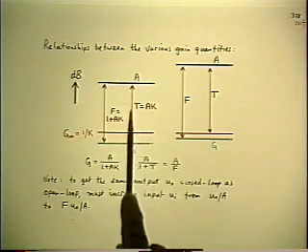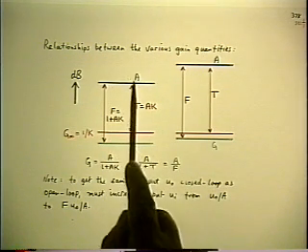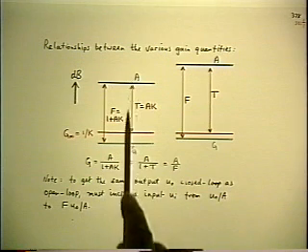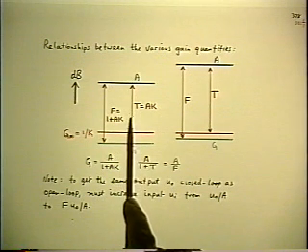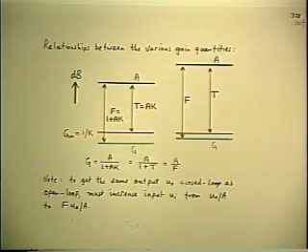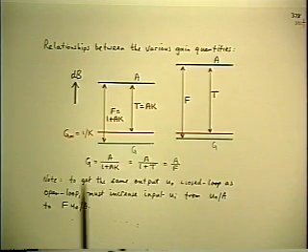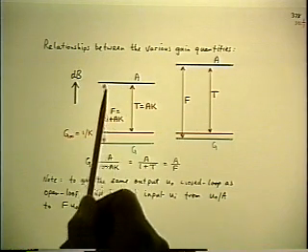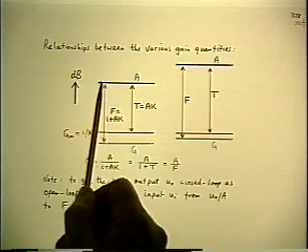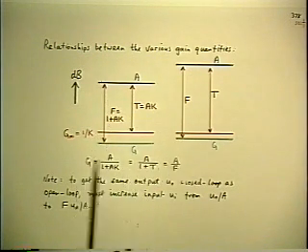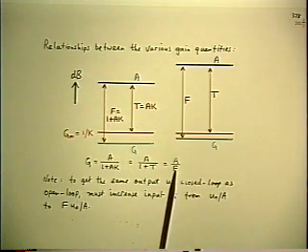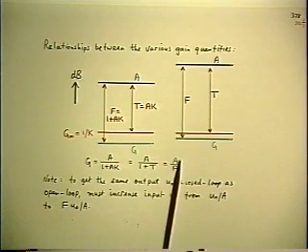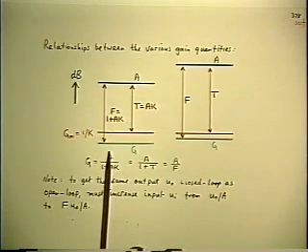So on the dB graph, the number of dB between the A line and the G infinity line is the value of T in dB. And for the same reason, the number of dB between the A line and the G line is F in dB, because F is the ratio of A to G.